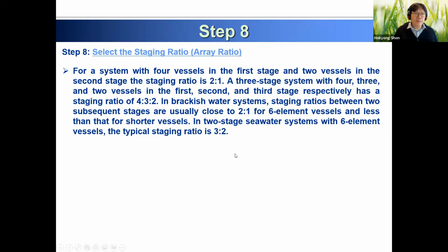So you can possibly design your seawater desalination as a two-stage system with a 3 to 2 staging ratio to achieve your water recovery of around 50%. So that's how you can get your staging ratio.